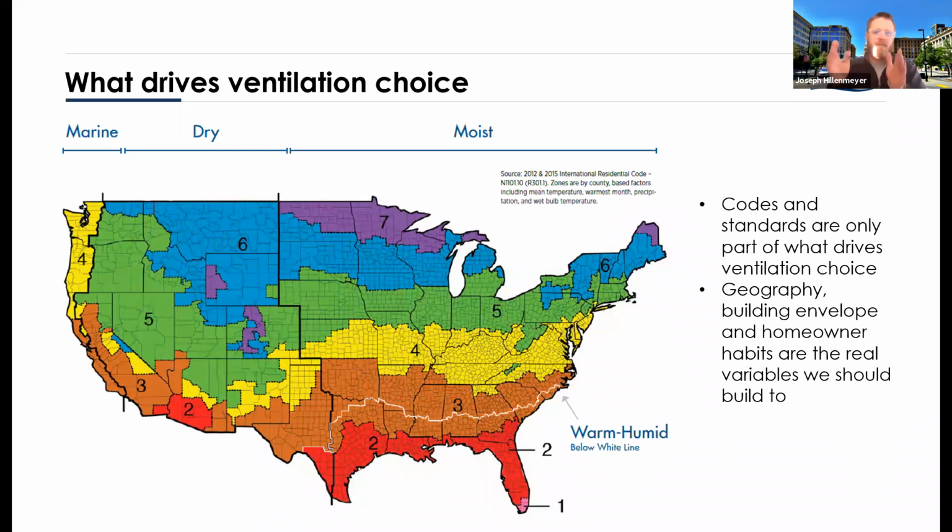There's a cabinet, and then different filters can go in there. You can go up to MERV 16, you can go down as well. But MERV 13, when it comes to PM 2.5, the one we're really worried about, does the trick. And technology has gotten to the point where we can keep the pressure drops where they need to be so that you're not doing any damage to energy goals or your system in general.